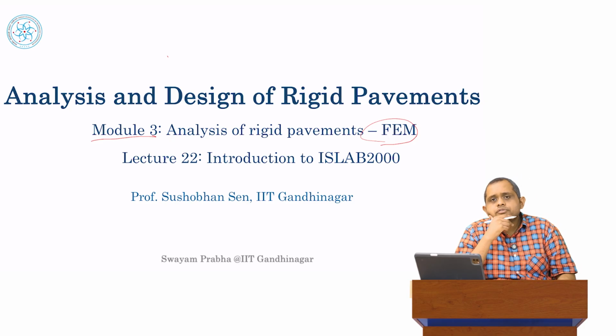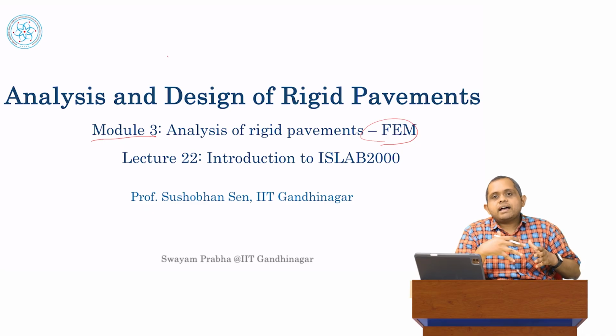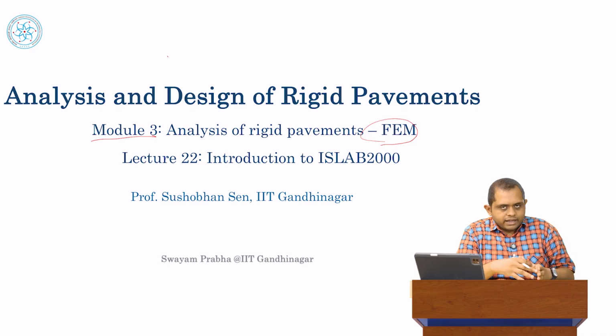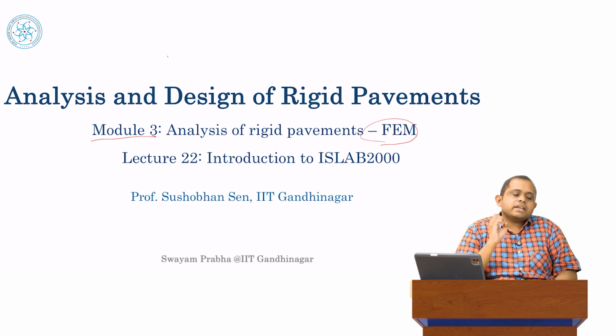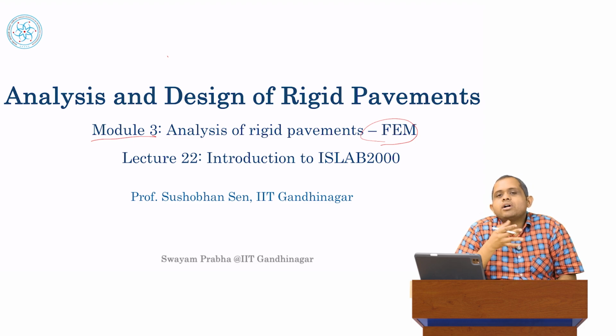The advantage of using the finite element method then is we completely let go of the unreasonable assumptions of the analytical methods. And now we have a method which can give us more accurate solutions without those assumptions with some error, but as long as we have enough computing power, the error will be relatively small. Remember, in practice, we are okay with small errors because when we're actually constructing these pavements, we have a lot of variability on the field.